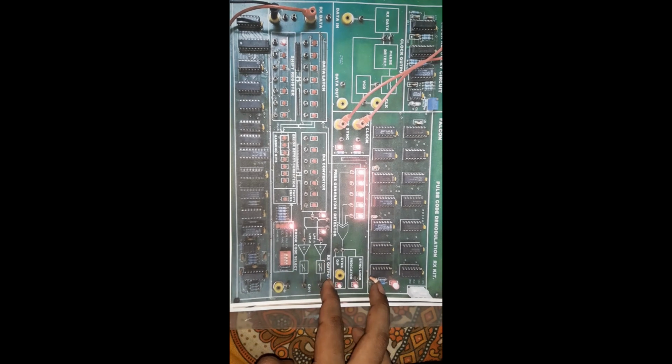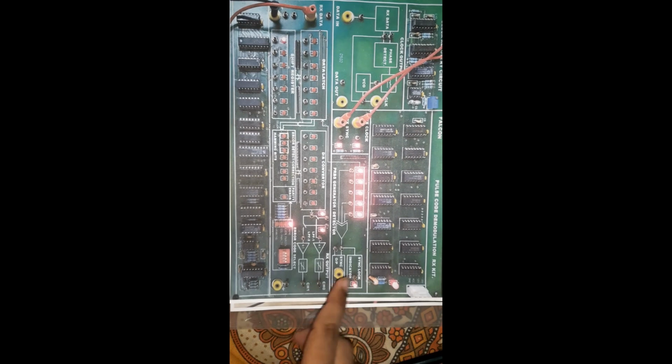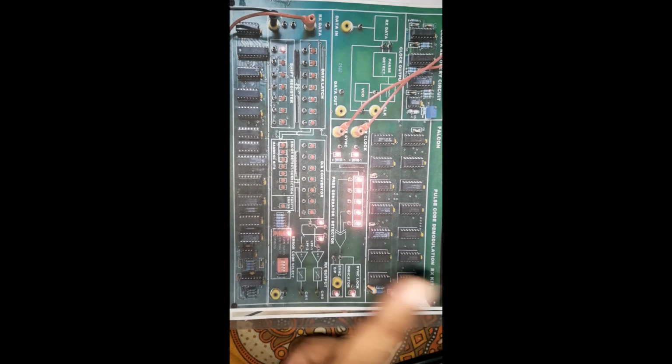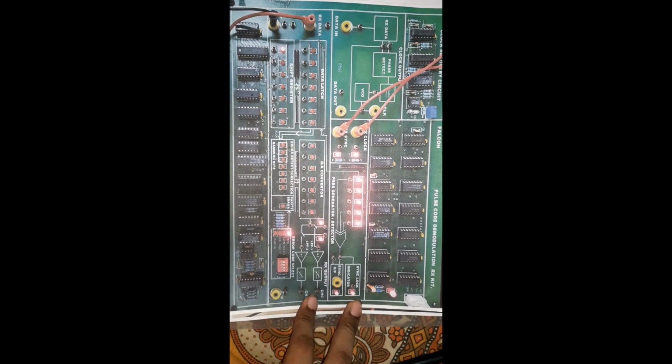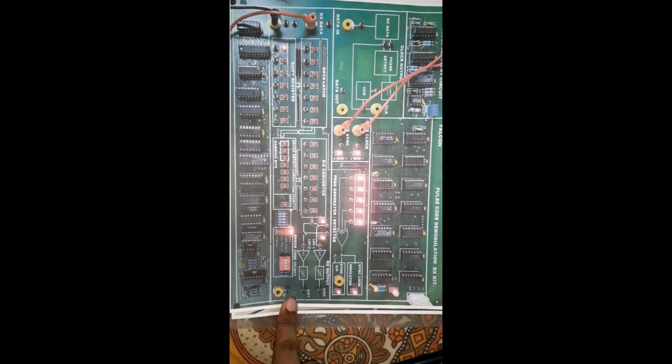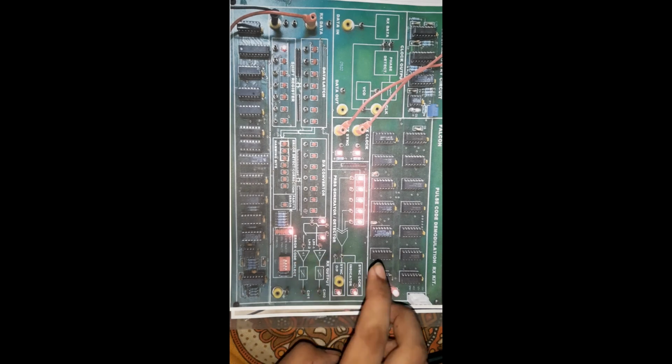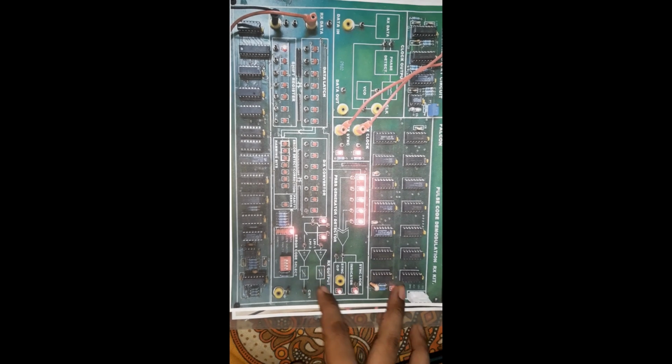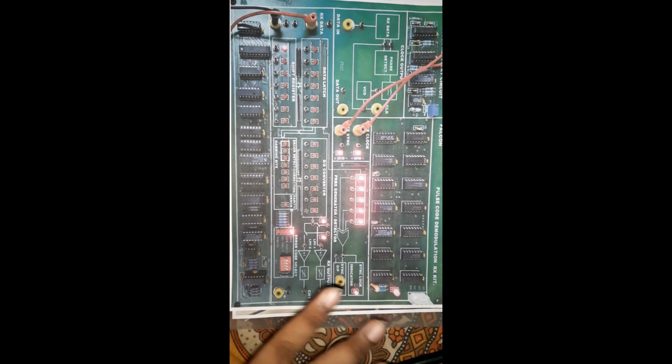See, from channel 0 you will find the signal that was connected to channel 0 of the transmitter side, and from channel 1 you can detect the signal that was connected to channel 1 of the transmitter side. That was 500 Hz and 1 kilohertz. The 500 Hz is detected from here, and the 1 kilohertz will be detected from here. The working of the demodulator circuit that I have already shown you in the block diagram is the same. You can see that there is an RX output shown over here. So there is nothing more about it.